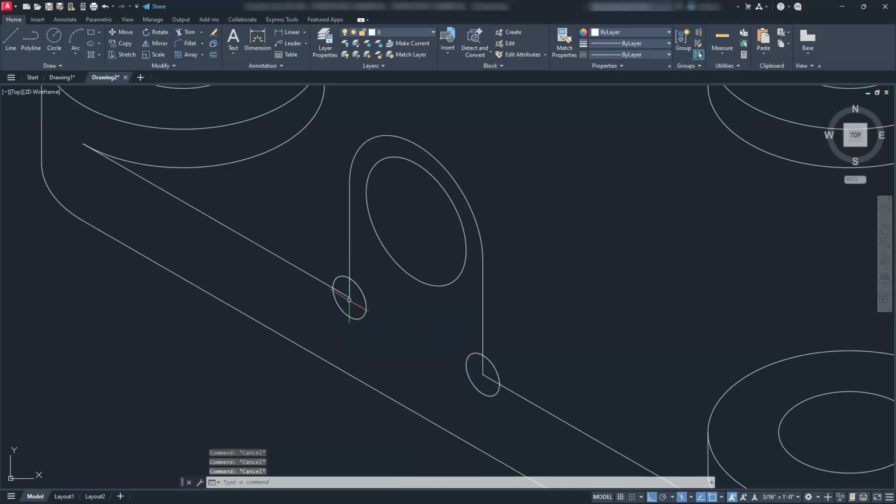Okay. Let's go ahead and move both of these iso circles that I just created. So I'm going to select them both, click here. I'll go up a distance of the radius, which in our case is going to be 5. Now I have to move these separately now. So I'm going to move this one going 5 this direction. And then I'll go ahead and move this one going 5 this direction, right? So now we have those fillets on there.